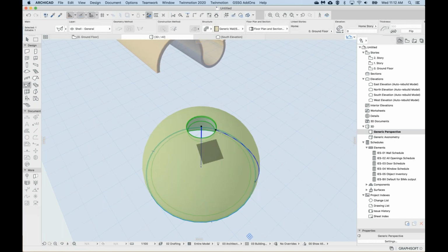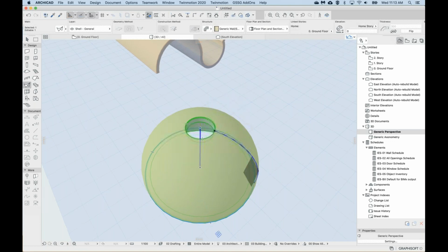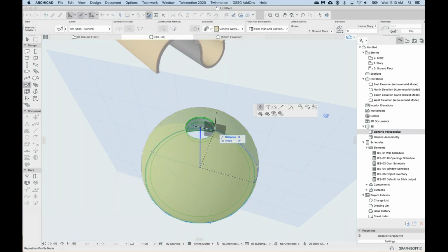Okay. So once we've got a hole, we're going to click again on the end of this profile. So not the axis, but the end of the profile. So the same point we moved, we're going to click on this again. So instead of using the drag or the move node, we're actually going to use the continue polyline. So the exact same method that we used for the extruded method. That's the fourth across. So the continue polyline.